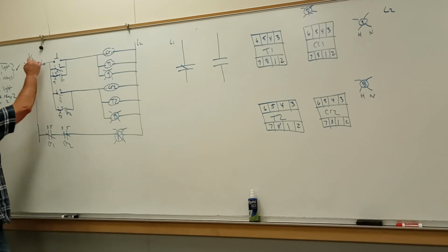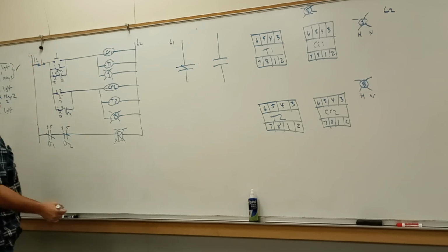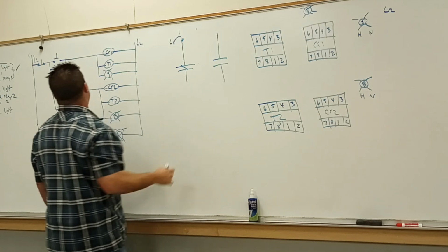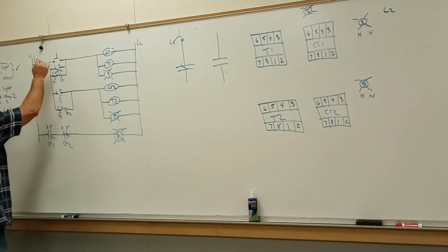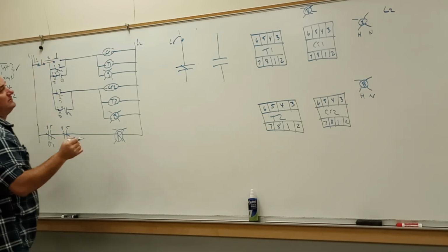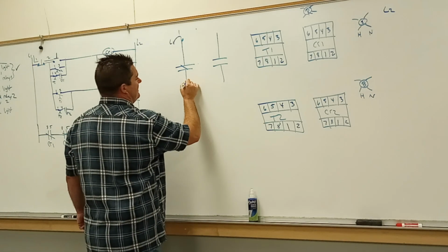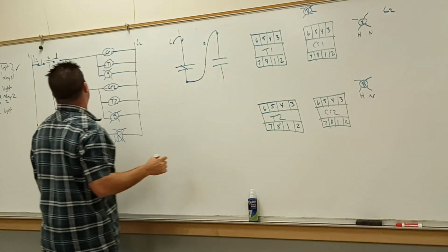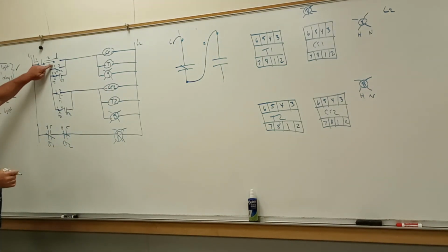So to match this wiring up, power into my stop, number 1. L1 into my stop, number 1. Out of my stop into my start, number 2. The end of my start, notice it hits the 1 and the 4, or the 1 on each of the relays.